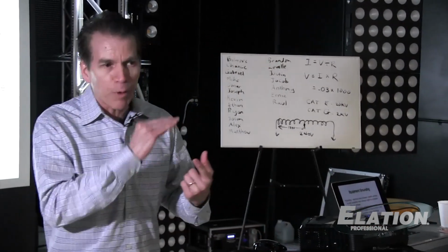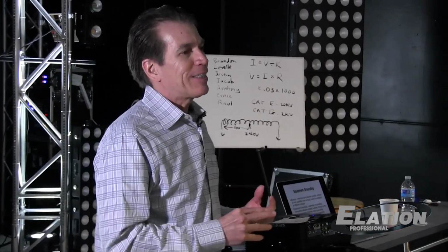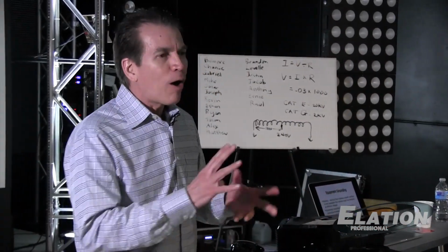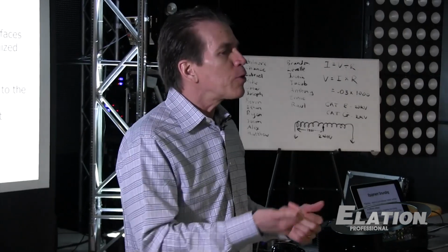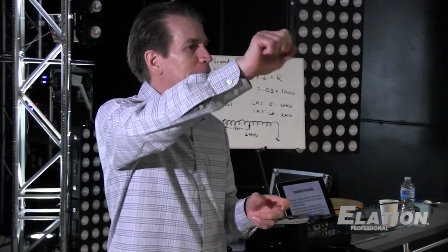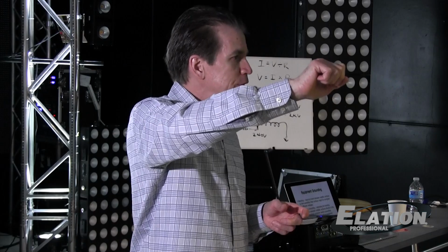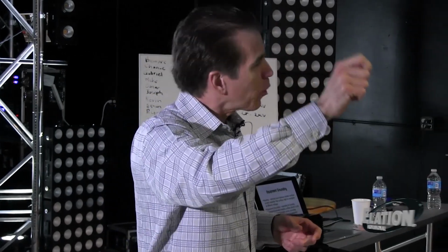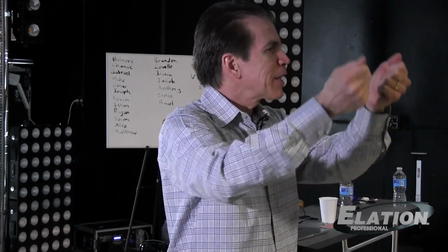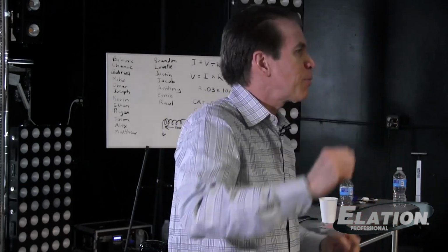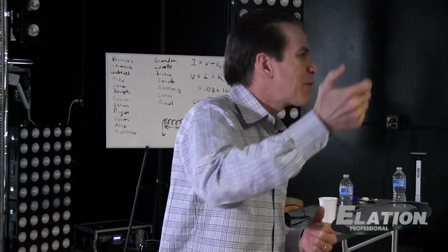So anytime you're setting up, whether it's permanently installed, or temporarily, or I should say portable, all the metal should be connected together. And you can take a multimeter that has continuity. So your meter has a dial on it. One of these settings is voltage. One is for current. Don't ever use your meter with the leads on it for current, because those leads can't conduct much current. Get another clamp meter for that.